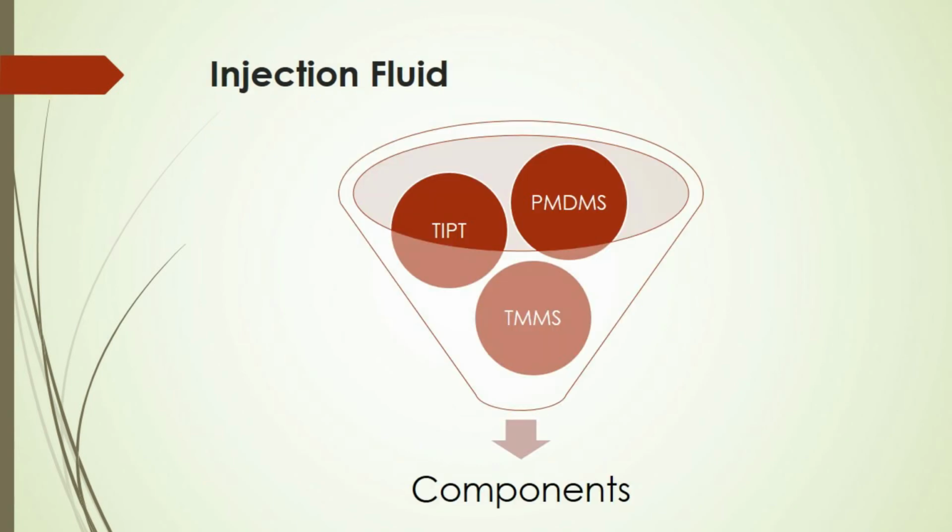Now, as seen in the procedures, the process of cable rejuvenation has largely concentrated on injecting silicone-based fluids into strands of aged medium voltage power cables. The injected fluids move through the cable to water-treeing places, react with water, and improve the insulation's dielectric qualities.